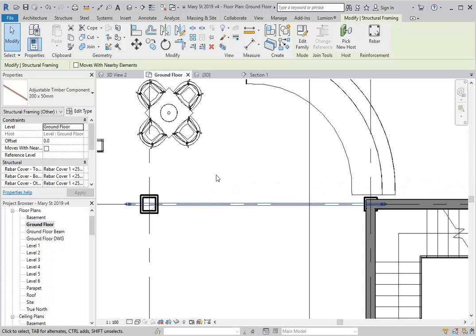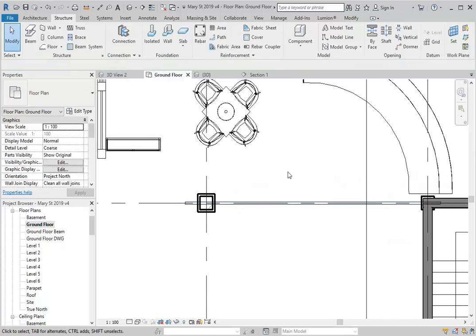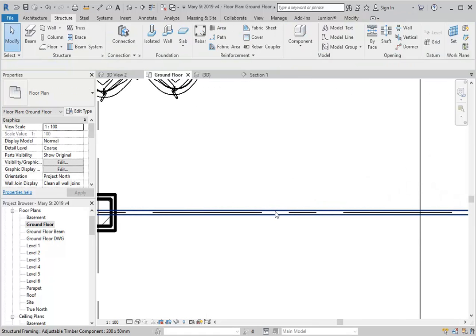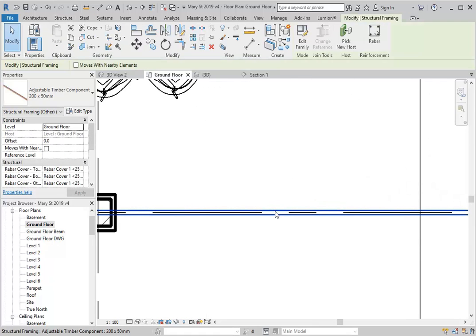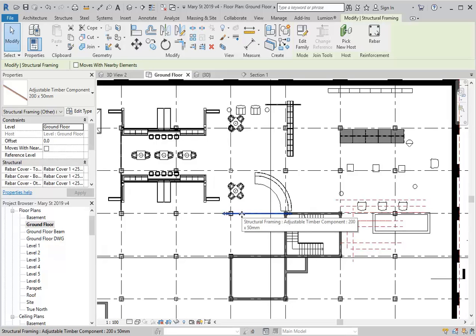Okay, so I made this family so that you can modify it really easily. It's easiest to place it in plan first, and you'll see it in your floor plan. If you're thinking that it's too low, you are actually spot on. It is too low. But it's better this way. If we place it on the ground, modify it, and then we'll lift it up afterwards. So it's on my ground, on the floor.